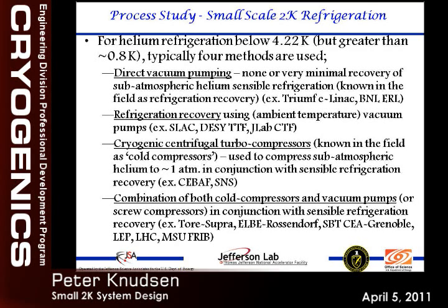I put up here a few of the labs that are examples of this. The direct vacuum pumping, TRIUMF is an example of that, Brookhaven ERL, refrigeration recovery, SLAC, DESY, the TESLA test facility, and JLab CTF is an example of that. And of course, for all cold compressors, the CEBAF and SNS are really two examples for that. And then for the combination, there's quite a few places that use a combination of warm and cold compression.